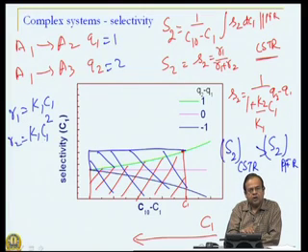So, the reduction in rate is higher for the undesired reaction, and whenever there is a higher reduction in undesired reaction rate, that is desirable. So, CSTR has lower rates of second reaction compared to their counterparts in a plug flow reactor, and as a result the selectivity in a CSTR is better than that in the plug flow reactor.